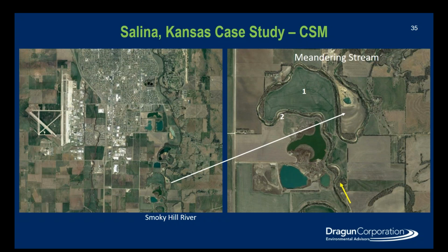Number 2 is the inside of a meander bend where you get permeable deposits. 3 is the outside where you get non-permeable deposits. 4 is a cutoff, and 5 is an oxbow lake, something that's been cut off, and you get low permeability material. So you get a lot of different materials aerially, and vertically you do. So it's very unpredictable what's where.